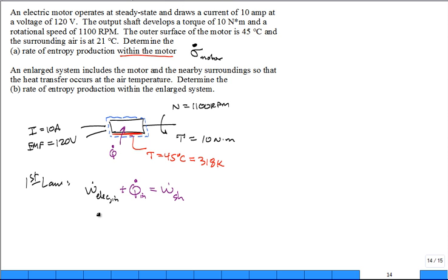When you do the computation, it's voltage times current, and then the shaft, so you find out it's 1200 watts coming in with the electric. It's 1152 watts going out with the shaft. And so Q dot in, I'm going to drop the in, just Q dot, negative 48.083 watts. It's the negative sign I anticipated. It's actually not into the system, but out of the system.